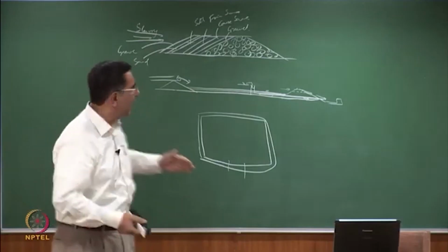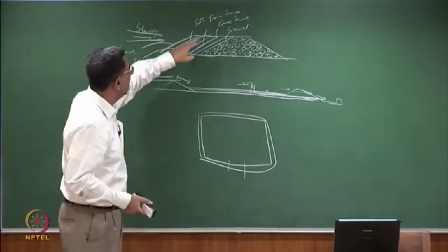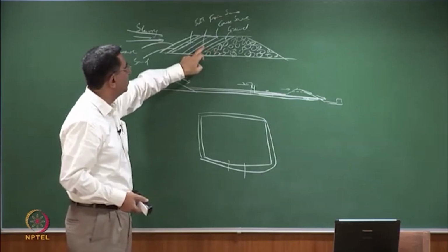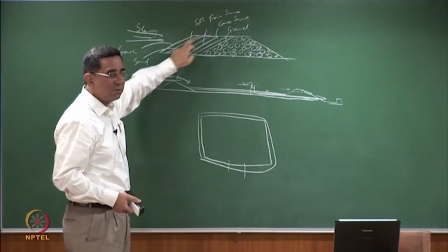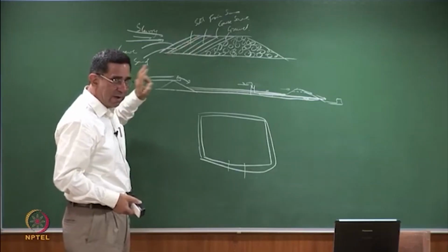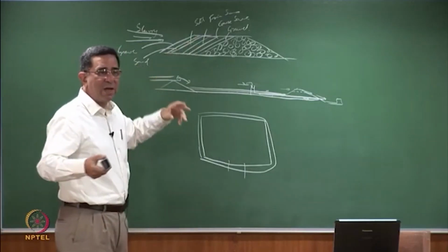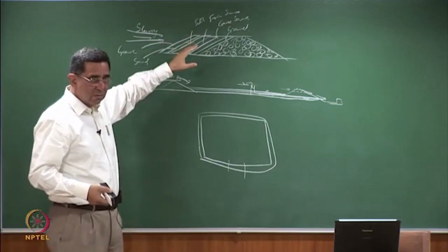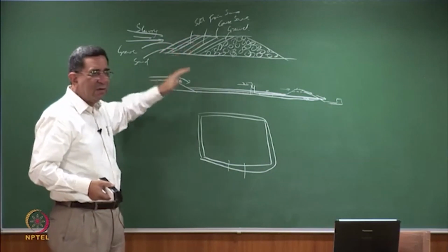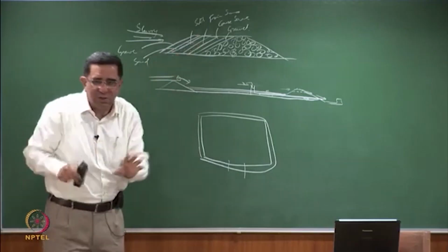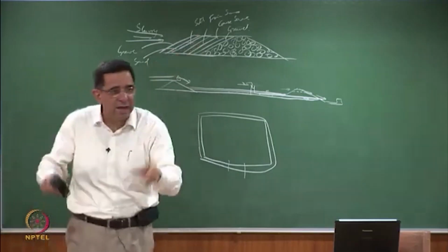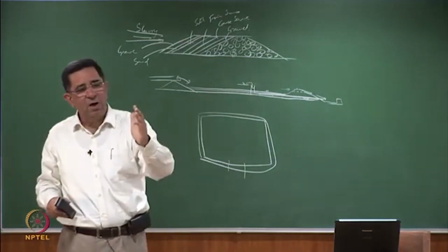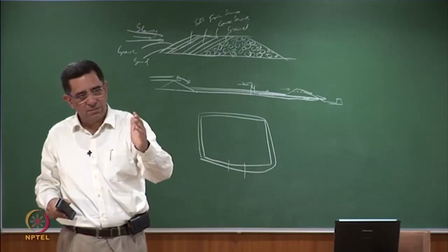You can come and say, sir, I don't agree with you. I will have cobbles, I'll have gravel, I will have coarse sand, I'll have fine sand. Instead of the silt, I'll put a geotextile filter. Right? And I will give you a geotextile filter which can remain exposed for the 5 years. Or if you are bothered about it, okay, on the geotextile filter you put some cobbles so that your geotextile filter is protected from animals, from man, from vandalizing. Right? So your silt particles will now come and sit in front of the geotextile filter.